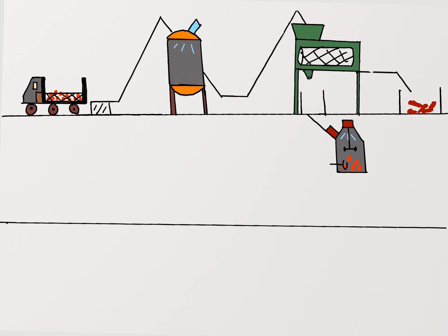The screw will restrict discharge from the cage, which creates a pressure within the cage. This controls the amount of de-oiling of the smashed digestion. The screw press lets out a liquor of oil, which contains impurities and also a press cake.